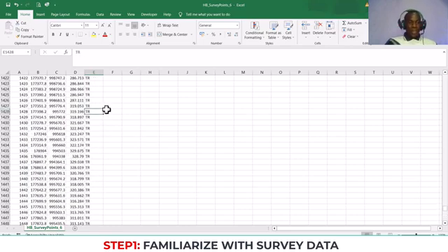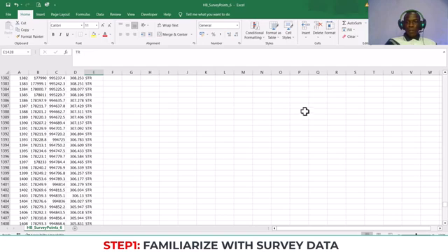I usually take the points for the trees, so that if I need to avoid cutting down trees, I will do that, because I will see these points in my workspace, which is important. I encourage you to always do that when you are designing. Take the coordinates of the trees so that you can preserve these trees. We don't want global warming. That's on a lighter note, but very important. So let's move on. This is an Excel file, but it will be saved as a CSV file.